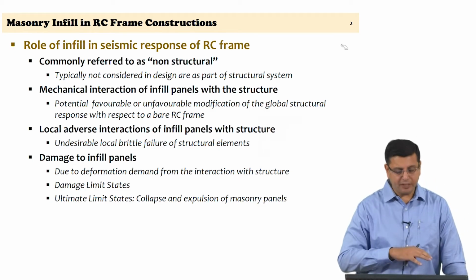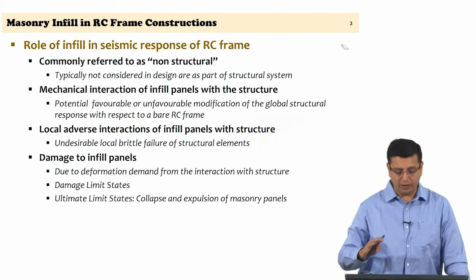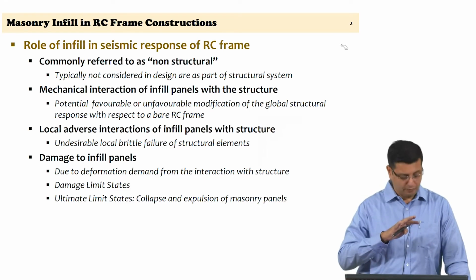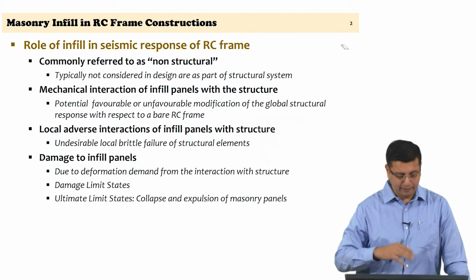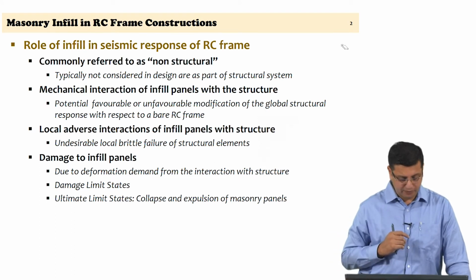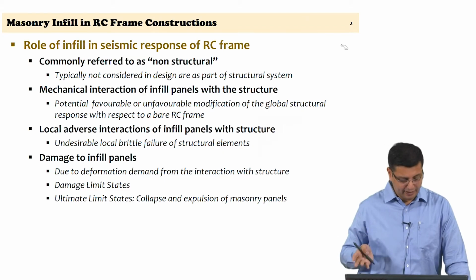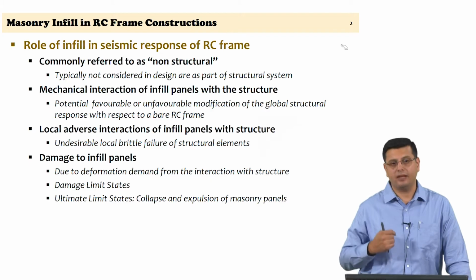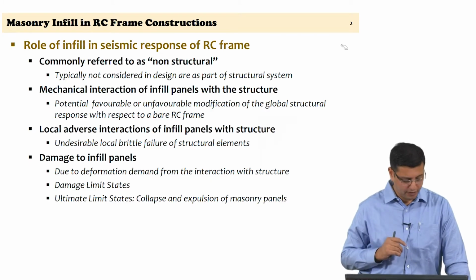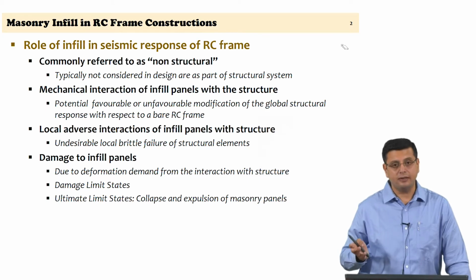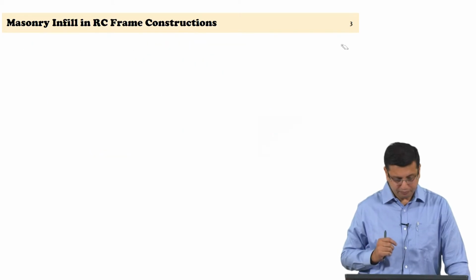So, the damage to infill panels needs to be understood within the context of deformation demand, which will have different effects in the panel and in the reinforced concrete frame. Damage limit states have to be identified, and in the ultimate situation, failure of the panel and collapse of the panel, expulsion from the frame is a potential falling hazard, which can cause a life safety situation.